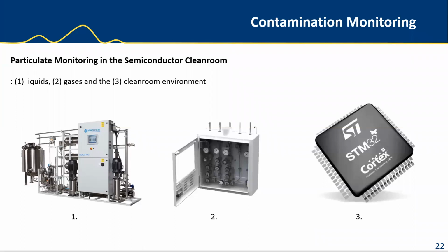From the risk assessment, the persons who undertake the assessment should have the experience and process knowledge to identify the weak points in the wafer fabrication process. If expertise is not available internally, then external consultants can help with the risk assessment. In the examples above, we see there are 3 applications where particle counters can be used to monitor: number 1 is liquids, number 2 gases, and 3 is the clean room environment itself.